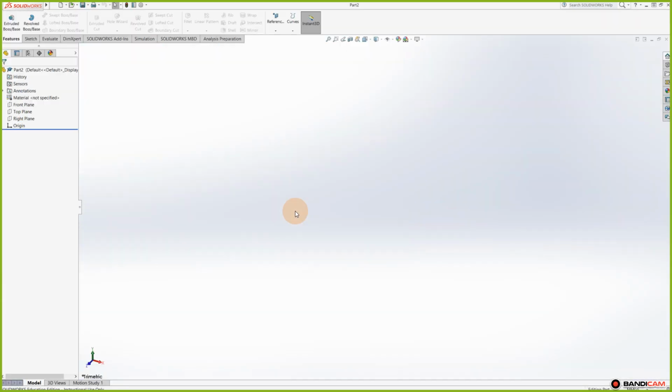Now, a lot of you may say, but Rob, how do we know what units we're using? This makes no sense. In Inventor, we have to choose different objects. Well, if you look at the bottom right corner of your screen, where you see my mouse, you'll see that you have the option here to change the different units of your drawing. So if you want it to be in inches, millimeters, centimeters, meters, they're all able to change at the bottom of your sheet over here. That's the first thing I want to show you guys. So you understand you can change the units at the bottom right corner.